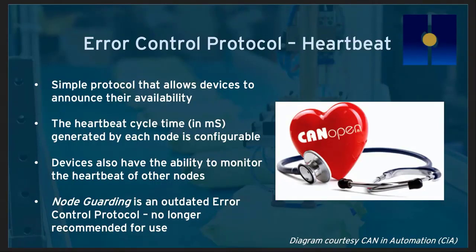There's another error control protocol out there called node guarding. There's nothing wrong with it per se, but it's pretty old-fashioned. So if you have your choice between error control protocols, just use the heartbeat. You don't need to use node guarding. It's pretty much outdated.